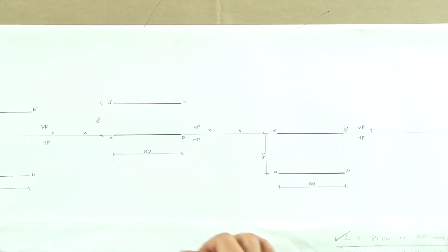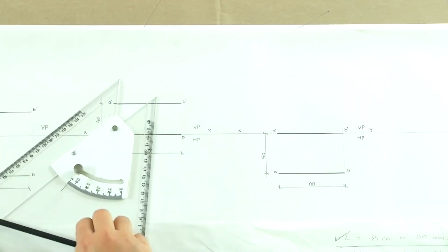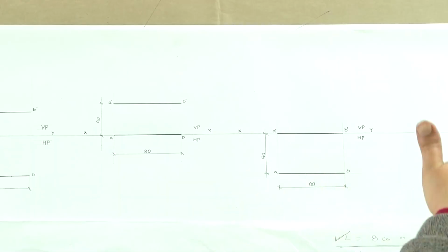Now, one thing which we also have to understand here is, what if we are seeing the projection of the line on the side planes in the elevation. Now, just imagine that this line, the same line, has to be projected in side elevations. So, what we have is this particular quadrant, first quadrant, and this line is in HP, it is in HP and it is at a distance of say 50 mm from the VP. This is how it will be kept.